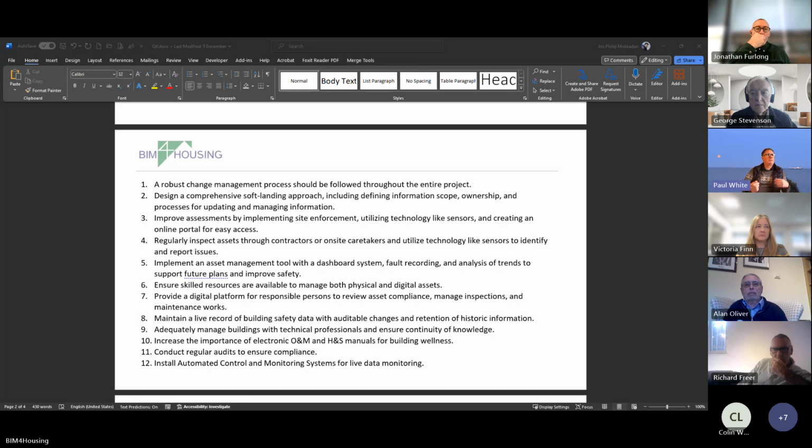And I think this is the bit that we're talking about. It's not live as such, but it's not far out of date, if that makes sense. Because if for instance you've got an AOV system and 2 of them have failed, you have no smoke control. These things are not as simple as we want them to be.